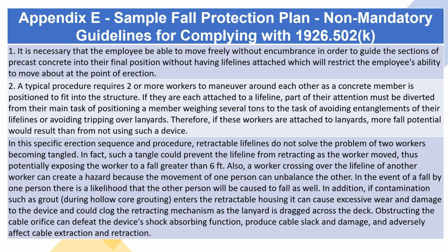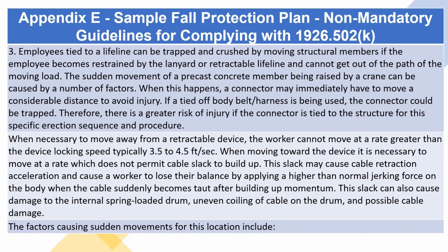In addition, if contamination such as grout, during hollow core grouting, enters the retractable housing, it can cause excessive wear and damage to the device and could clog the retracting mechanism as the lanyard is dragged across the deck. Obstructing the cable orifice can defeat the device's shock-absorbing function, produce cable slack and damage, and adversely affect cable extraction and retraction.